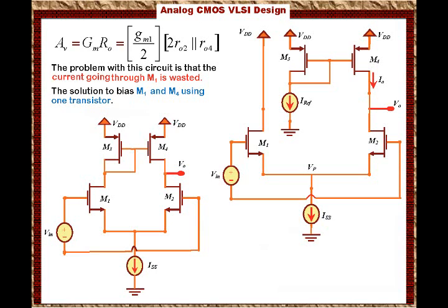We have to make sure that M3 is a mirror of M4 because you want the circuit to be as symmetric as possible. Then always I3 equals I4, right? This is the requirement we have to have. Otherwise the circuit will deviate and you will have some problems, right? Because the current ISS must be split in half between M1 and M2, and then the currents through M3 and M4 should be equal. Then we have to say that M3 and M4 are mirror images of each other.